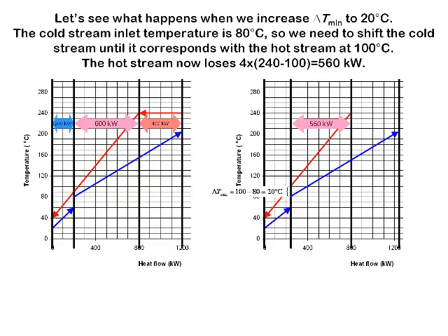This means that the rest of the cooling of the hot stream will now require 240 kilowatts of cooling water. Similarly, our cold stream, the rest of the heating required to bring that up to its target temperature of 205 degrees C is now 440 kilowatts.